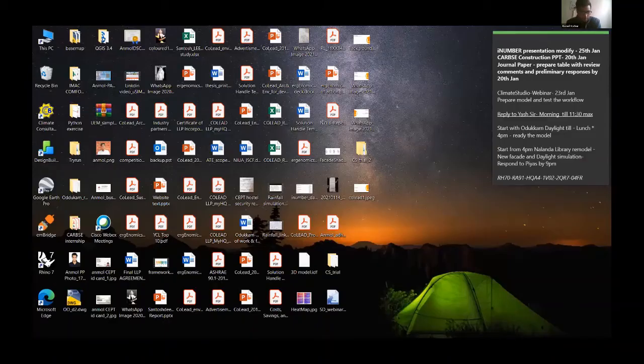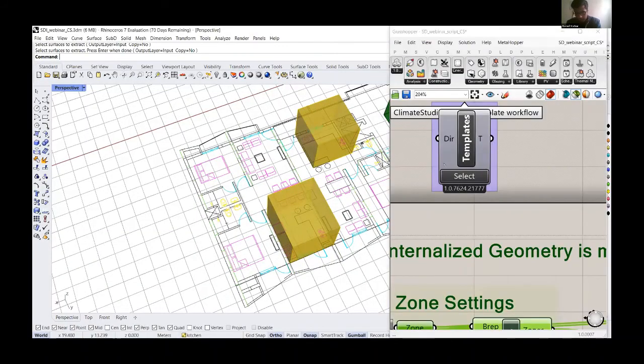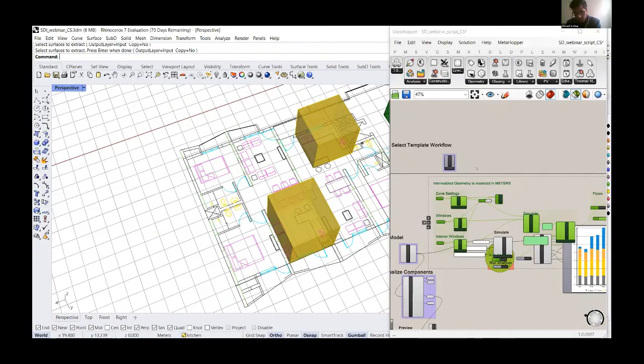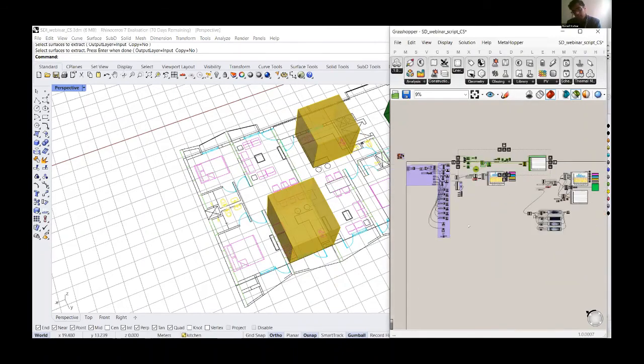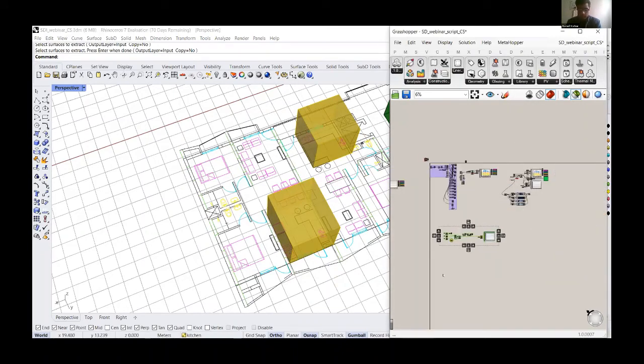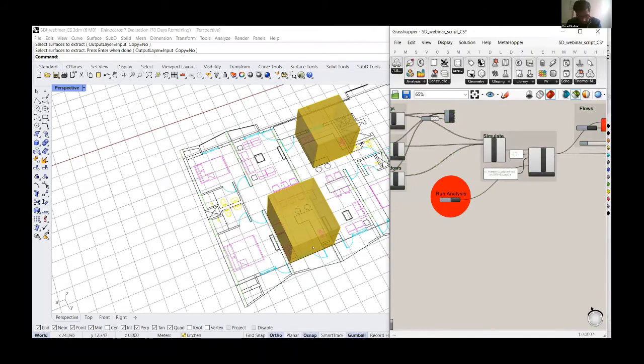The basic difference between zone ventilation and an airflow network is that ventilation is calculated more accurately, as you would in a CFD model. You will have different pressure and wind velocity coefficients at each boundary of your zone. Airflow network also calculates these at different intervals, not as refined as a CFD simulation, but fairly more accurate than the regular ventilation method.